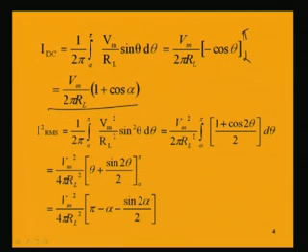And if we want to find out the RMS value of the current, then we have to do it according to the way RMS value is found out. So, the square of the RMS value will be 1 by 2 pi integration alpha to pi of the square of this expression, Vm square by RL square sin square theta d theta.